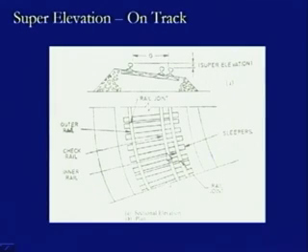And this is how it maintains the safety, otherwise there will be derailment of the wheel at this location, whereas there will be overturning of the wheel on this side, or the overriding of the wheel on this side basically. So, these two phenomena which could have been induced will be eliminated as soon as the check rail is provided at this location. And what we see, this is a plan, and in this case this is the elevation where we can easily see that the inner rail has been provided at the same elevation as on the straight section, whereas the outer rail has been raised.